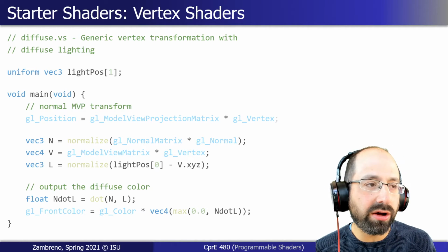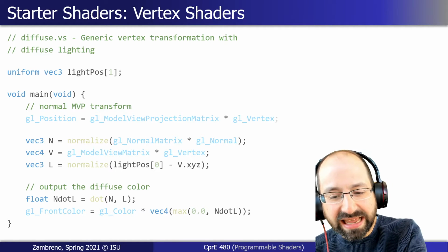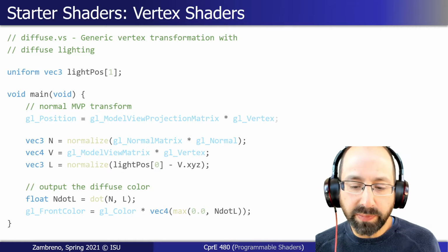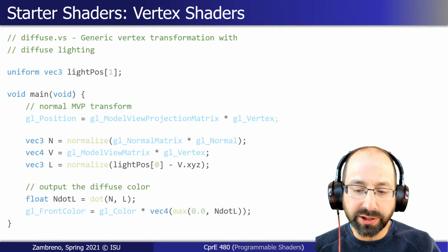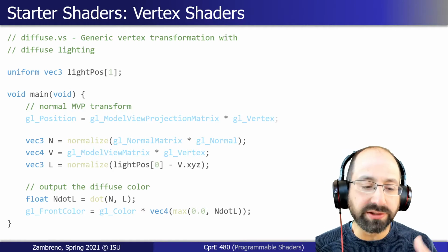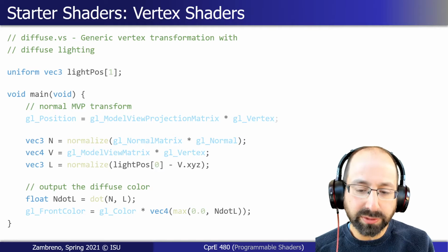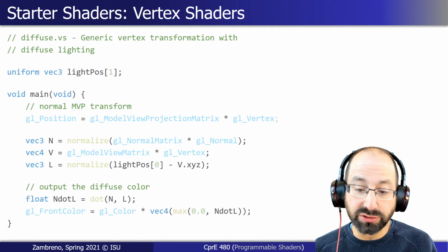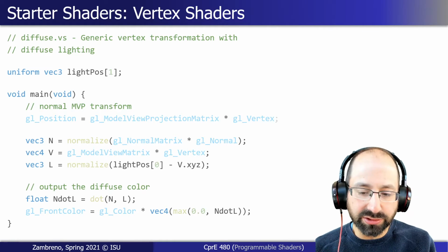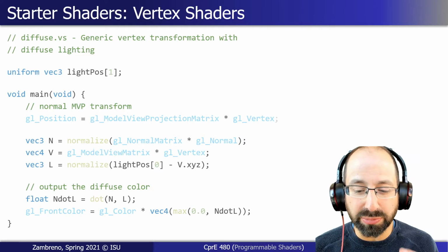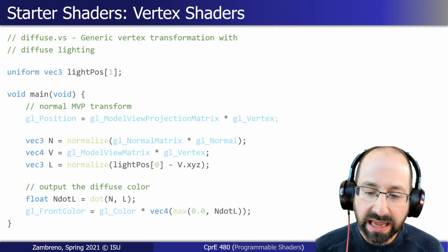So when we talk about how the shading language is something of an API, it is also something of an ISA. There is a lot of overlap there because the two things do tend to co-evolve with each other. If these operations are seen as critical from an API perspective, mathematically we're wanting to do normalization over and over and over again, then it stands to reason that from the hardware manufacturing perspective and designing the architecture, there's a good reason to have normalization as a built-in instruction with its own functional unit on the chip. But there's no guarantee that's the case, because for all of these operators, there's multiple ways you can do it. And we've started to see that.